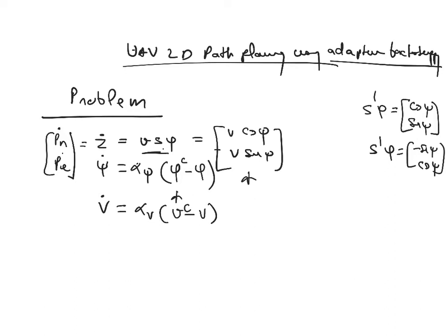So this is what you do, right? What commands do you give in autopilot? You say, hey, fly at this heading. So you always give a commanded heading to the UAV autopilot. You buy an aircraft, and the autopilot will take these commands: what height you should fly. If you see the chapter 6 assignment, what are the inputs? The heading, course angle, the height which you want to fly, and then the velocity at which you want to fly. So that's the simplest UAV. So we have 4 states in our system now: Pn, Pe, psi, and velocity. Okay, so that's the thing.